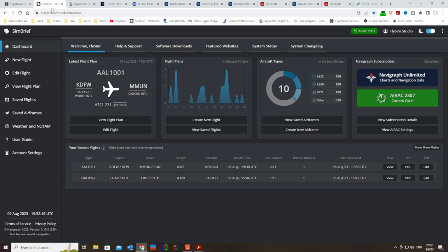It might come to a decision that we are going to dispatch our aircraft using ETOPS 120, but it might happen that we carry this much fuel on board, which will not be enough because of weather deviations that we might have to instruct the crew to do, and we might end up diverting for a technical landing into a suitable airport. Or you delay your flight, because it's out of the organized tracks, you don't have any problem, or you delay your flight until the weather improves,